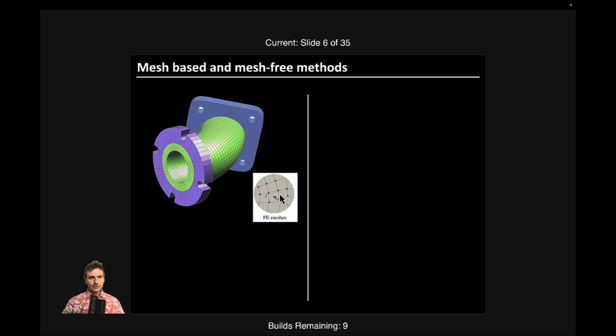They are called shape functions because we are usually in an isoparametric element formulation, and in that case, they represent essentially the geometry as well of the element. So, we have polynomial elements, polynomial functions, and so on. So we can just simply do that and compute, and we have now a shape function everywhere which is used to interpolate inside the element.